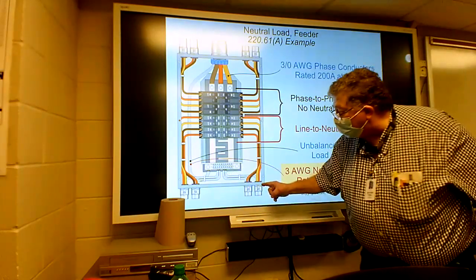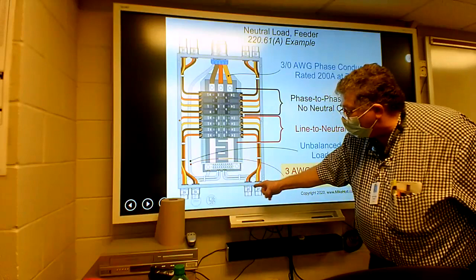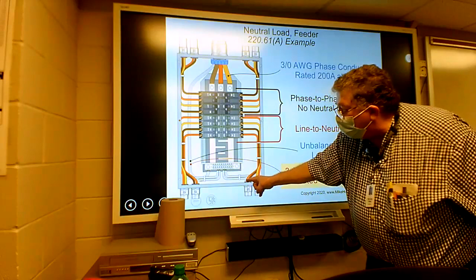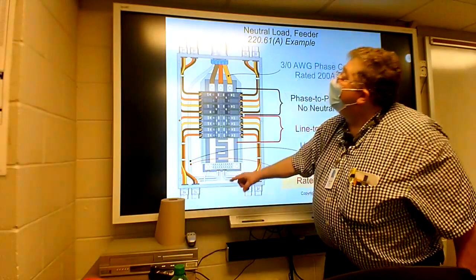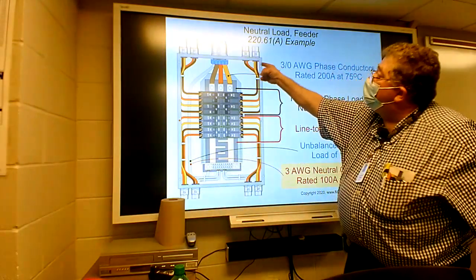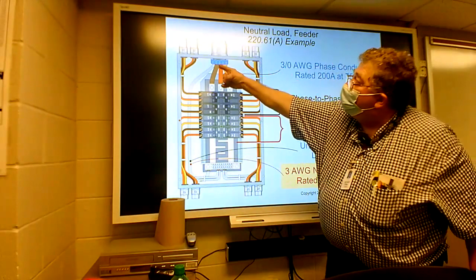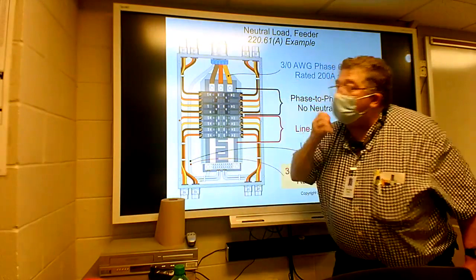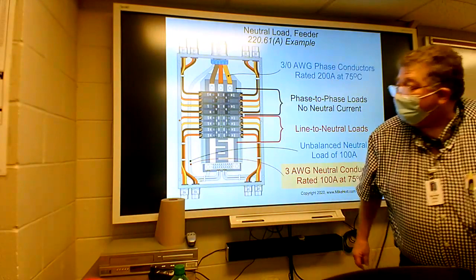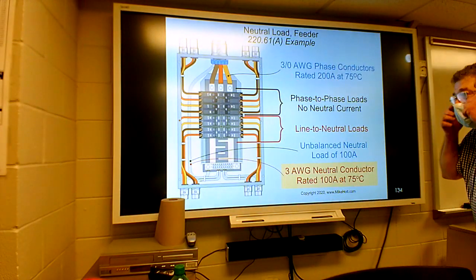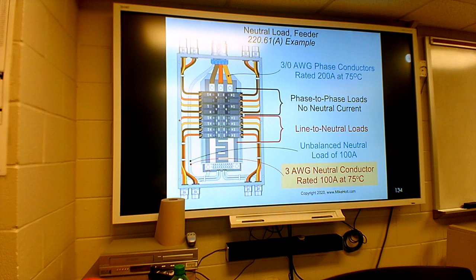This conduit does have a neutral in it plus 2 hots. 2 hots and neutral. 2 hots and neutral. 2 hots and neutral. But all of your loads up top, every one of them, all 4 of those up top, they're just line-to-line loads. No neutral. Okay, so the calculation goes like this.